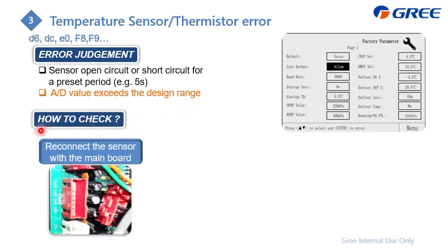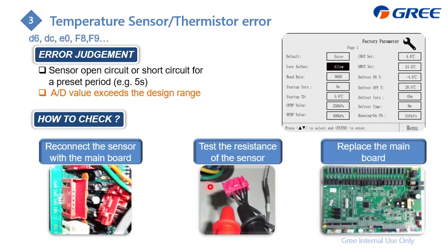First, how to check: we check the sensor connection to the PCB. We're just afraid that maybe this connector is not connected that well, which also leads to this malfunction. Next is to check the resistance value and compare it with the standard one. If it is almost the same, that means it is okay. But it is not that easy, especially to memorize the standard value. So here is how we do it in China.